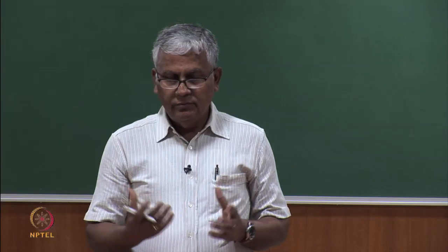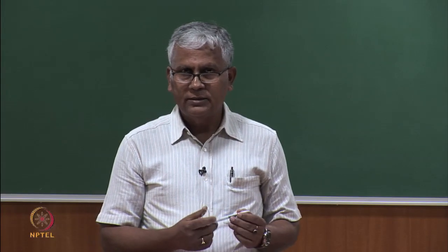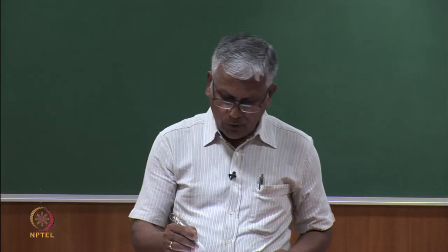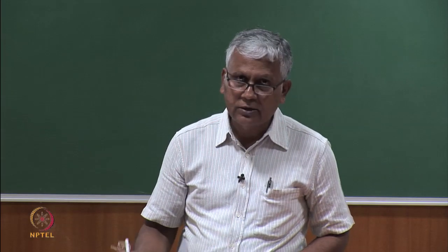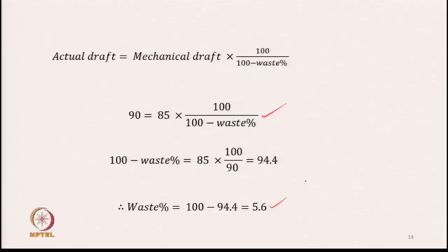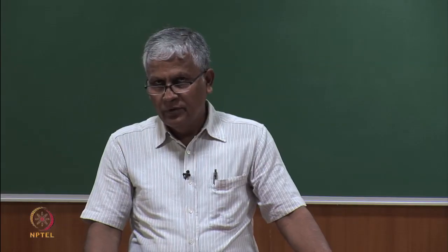If the waste percentage is 0, let us say, if we look at the expression at the top and put the value of waste to be 0, what do we get? 100 by 100 minus 0, this part of the expression becomes what? 100 by 100, hence it becomes just 1, and therefore, actual draft becomes equal to mechanical draft.